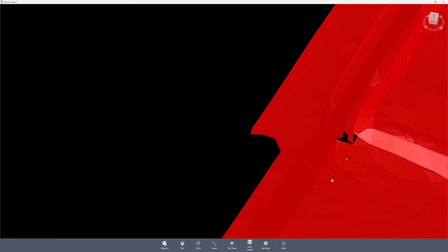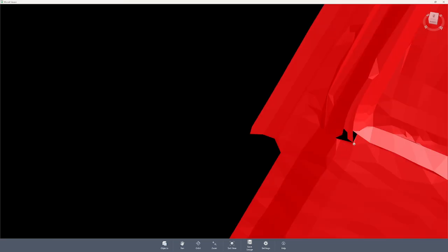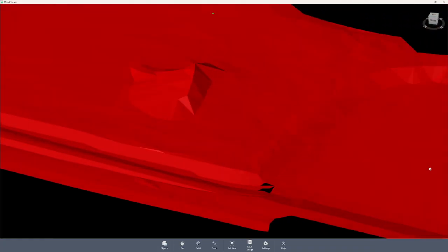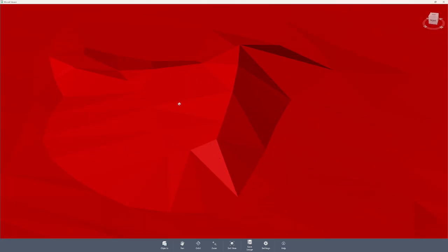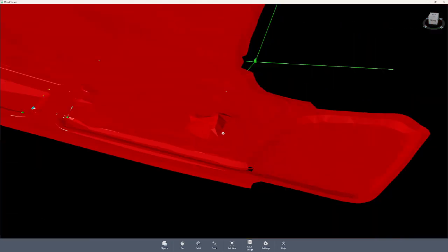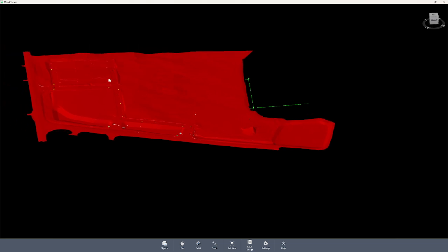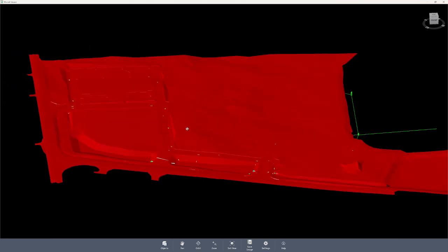Now I notice here that there's no surface right there. Most likely at some point someone went in there and edited the TIN and deleted lines, and that is why that surface is gone. But over here, this is a dirt stockpile that they had originally, so it shows up. As long as we have it on our surface, it's going to show up. So that is the Model Explorer. Again, we mentioned it once before.